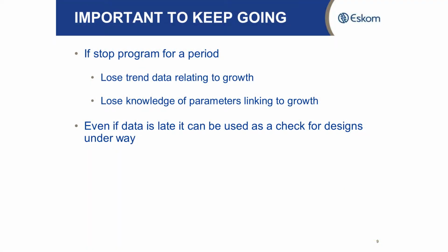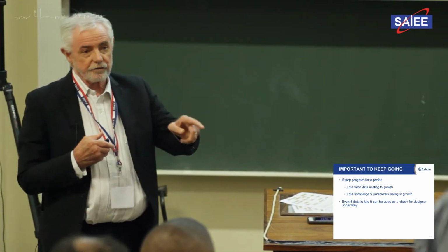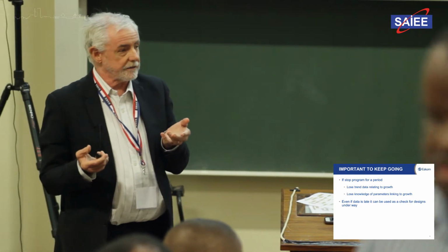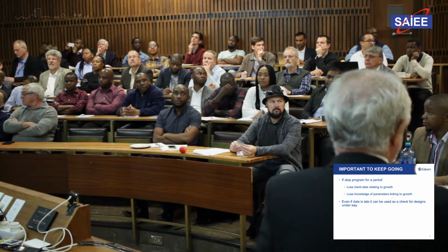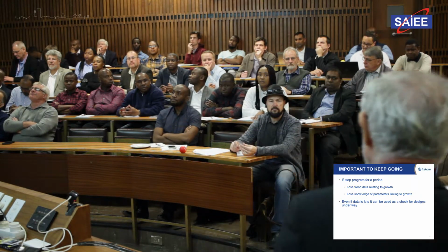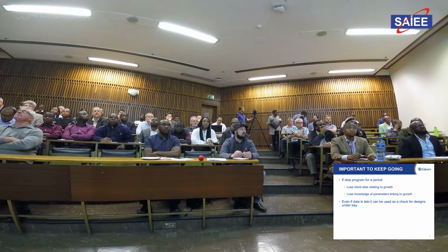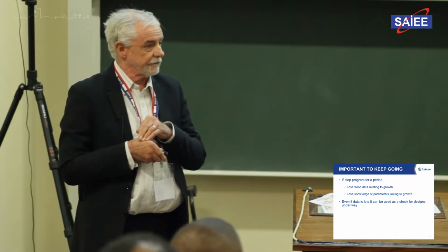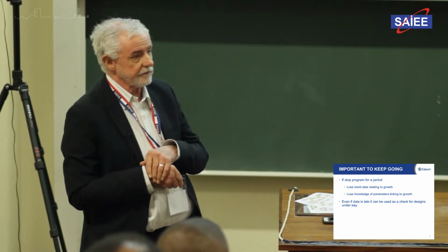Now, it's important to keep going. The problem with load research is, if you have a gap, it's very hard to fill in the gap of missing data. So you then have to make assumptions to cover the gap. And if you do that, you don't know whether it's linear or non-linear. How did you get from one to the other on the growth? Were the parameters changed? Did more people come in? Did they change appliances? There's a lot of stuff you don't know. So if you think, we've got enough now, we'll stop for 10 years and come back, you're most probably going to have to go through a learning curve again of about 3 to 5 years before you start getting accurate results again.